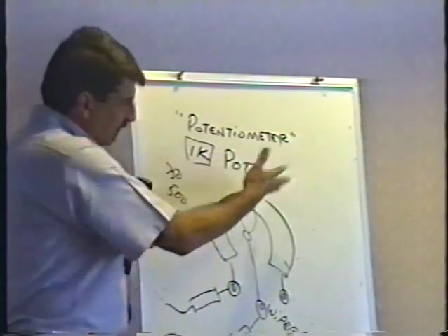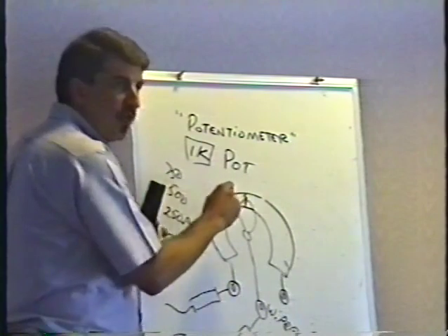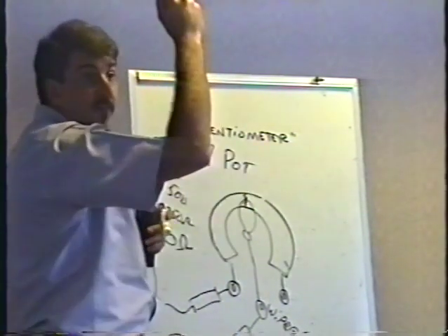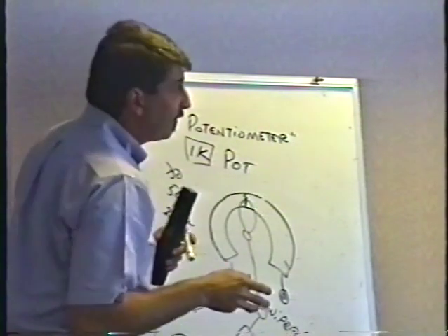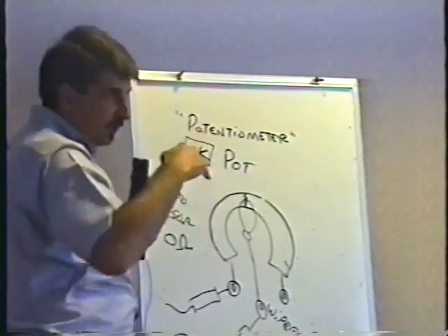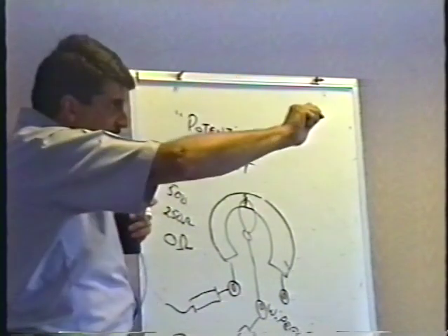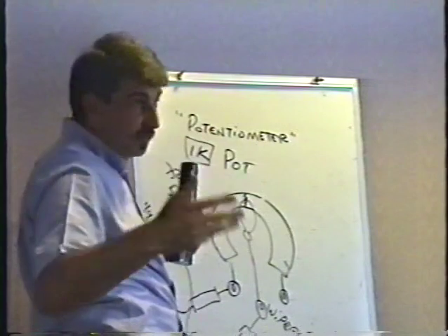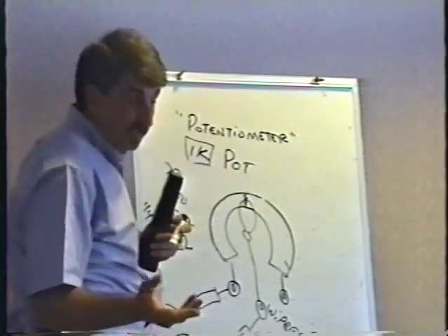And it sits in one spot for years and years and years, and eventually it cracks and causes no picture. And then you barely move the pot, and it comes back on full blast. If you ever have a problem where you're trying to adjust something, and you just barely move the pot, and the size or the volume or whatever it is that you're adjusting, and the voltage jumps like crazy, the pot's bad.